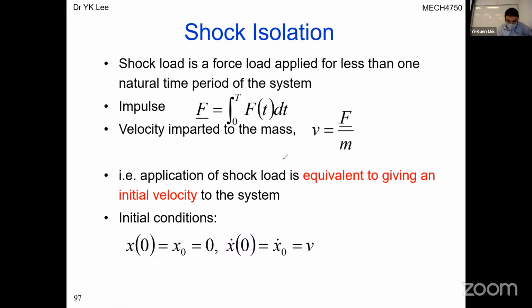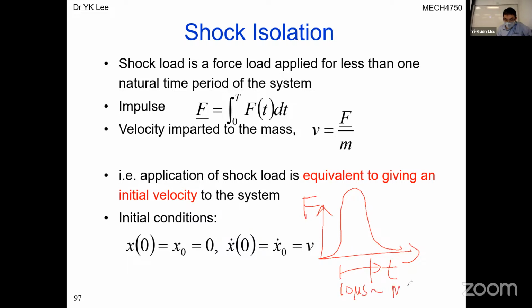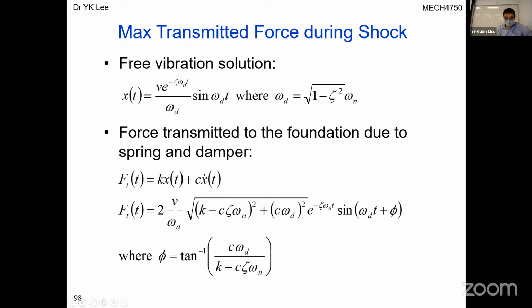So basically, in a short period of time, you have this time and this force, right? So that here can be on the order, I would say, 10 microsecond to about millisecond, right? It depends on what kind of machine. Now we try to examine the kind of shock problem. In general we study this, and then if you assume a single degree of freedom system, we can study the maximum transmitted force during the shock.